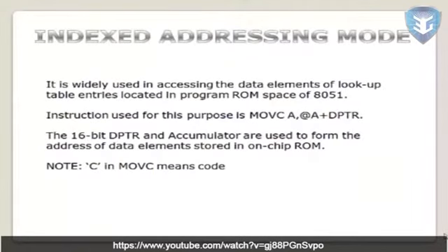Indexed addressing mode. This mode uses a base register, either a program counter or a data pointer, and an offset, generally the accumulator. Jump tables or lookup tables are easily created using indexed addressing. For example,